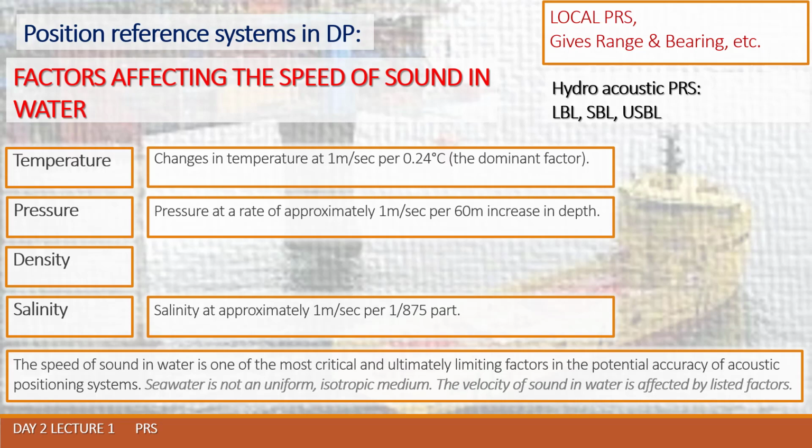And when I say calibration, it means that a special vessel arrives at the location and installs the test beacon. Then, at a distance of 1.5 times the depth away from the beacon, the vessel makes circles for an estimated period of time, checking the response of the beacon, and salinity is also checked with samples at different depths.